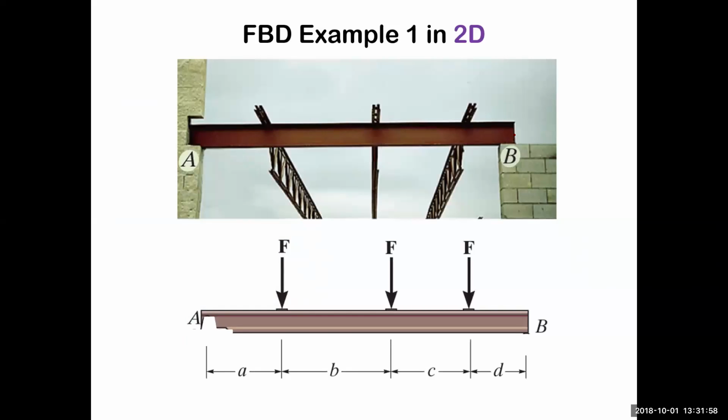Oh, yeah, so we remove those supports and replace them with the reaction forces, like FAY and FAX. There could be an FAX, although in some problems there's not often a need for that. Maybe the weight of the beam will be given to us, so we would add that in the middle. And then we would also have just a vertical force Y there. The reason we have an FAX is why? Why is there an FAX on the left but not on the right?